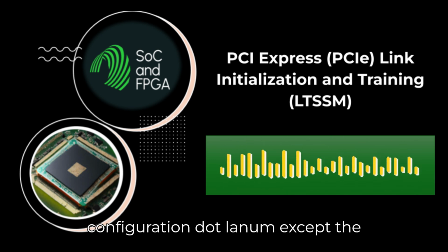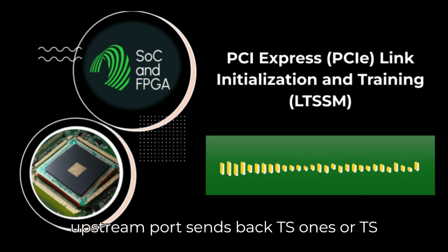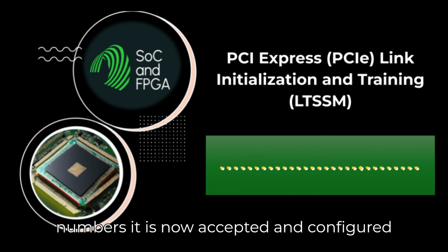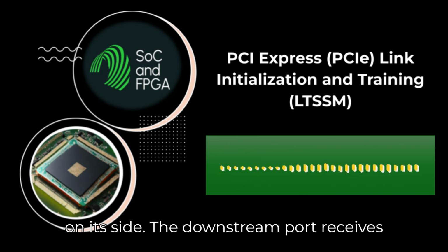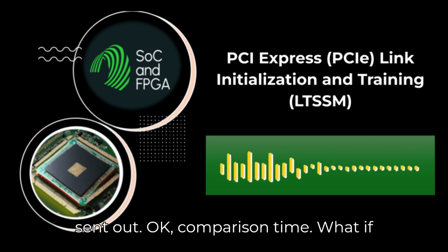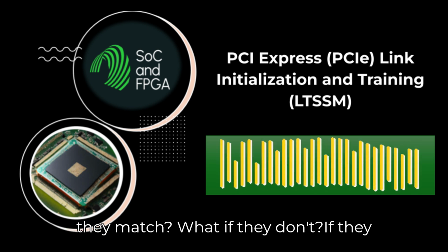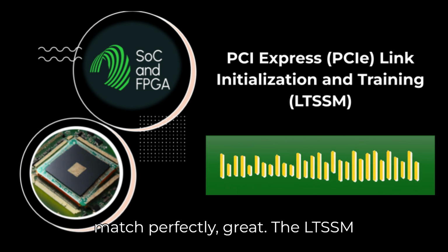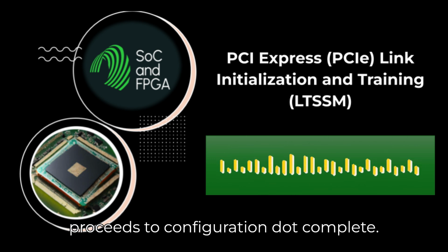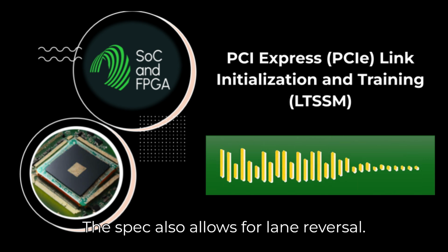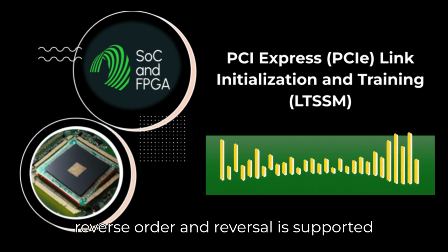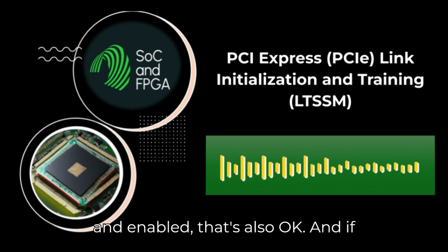Precisely. In Configuration.Lanenum.Accept, the upstream port sends back TS1s, or TS2s, echoing the link number and the lane numbers it has now accepted and configured on its side. The downstream port receives these and compares them to the numbers it sent out. Okay, comparison time. What if they match? What if they don't? If they match perfectly, great. The LTSSM proceeds to Configuration.Complete. The spec also allows for lane reversal, so if the numbers match but are in reverse order and reversal is supported and enabled, that's also okay.